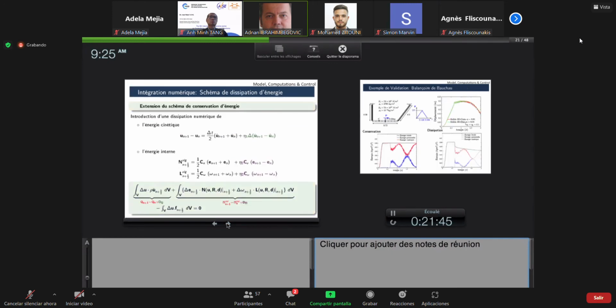Then we saw also that if you have an event that triggers high frequencies, then it's kind of desirable to suppress this participation of high frequency. So I just focus on this constitutive rotation. If you have a high frequency, the difference between the value at n and the value at n plus 1 could be quite high. So typically you take it out with this coefficient and you take it out from your computation. Whereas if you have low frequency, given the time step, the difference between the strain at n and the strain at n plus 1 will be very small. So basically, you're not going to modify the low frequencies.